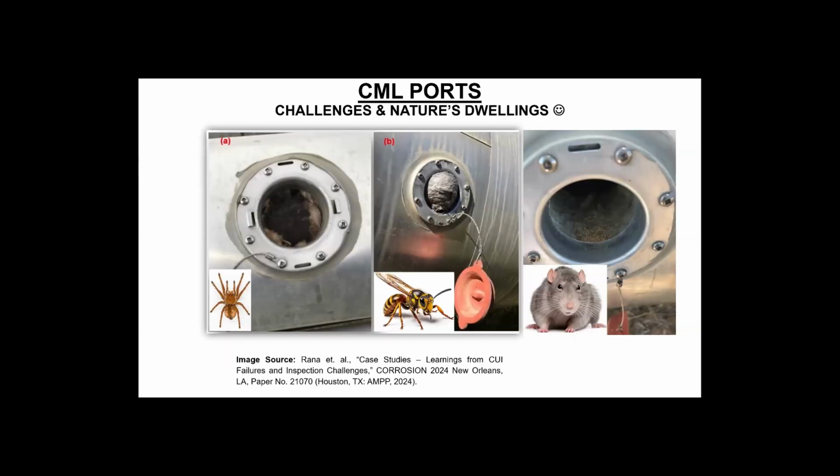And here are some few interesting examples. While API is clearly saying that we need to keep the inspection ports and plugs, we need to reseal them as soon as possible. It's imperative to do that. But in real life, what happens is the plugs which are meant to seal those openings fall open by themselves, because they are just like a friction fit into that cavity.